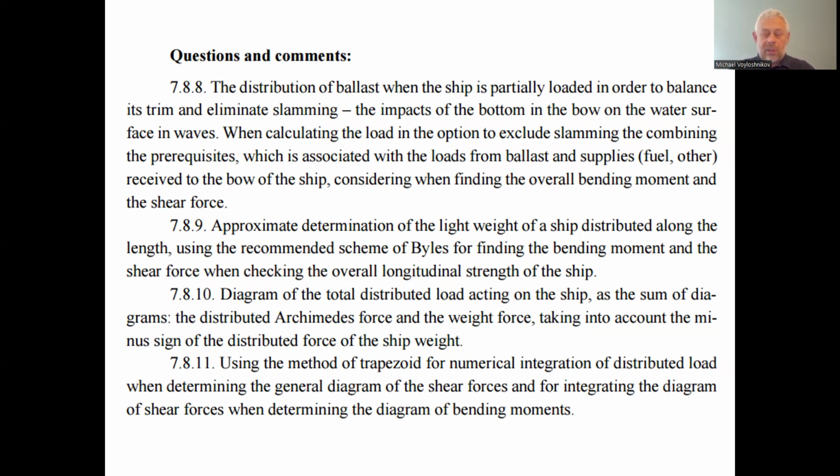7.8.10 Diagram of the total distributed load acting on the ship as the sum of diagrams of the distributed Archimedes force and the weight force, taking into account the minus sign for the distributed force of the ship weight. This is perhaps understandable, no big deal. We only have to know how to find the distributed force, as there is a difference between the Archimedes force directed upward and the load force directed downward. The result will be the distributed load action on the ship, which causes the shearing force and the bending moment, the general bending moment of the ship hull.